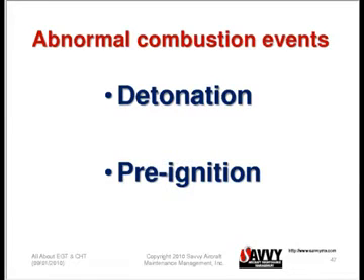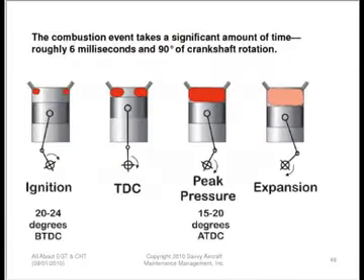One reason for that is that rising cylinder head temperatures can be indicative of an abnormal combustion event that could actually damage the engine unless you arrest it. The two abnormal combustion events we normally focus on are called detonation and pre-ignition. They're often confused with one another. They're quite different, and one is more harmful than the other, and we'll take a look at that.